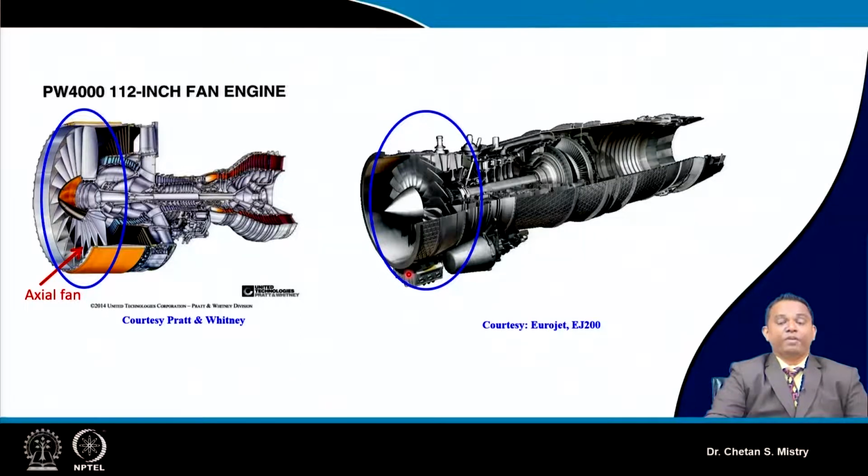speed. When my LP compressor or the fans are rotating at high speed, it may be possible that my entire blade is acting under supersonic condition. So that's the reason why, suppose this is made up of 3 stages of fan, all the 3 stages are of transonic nature.